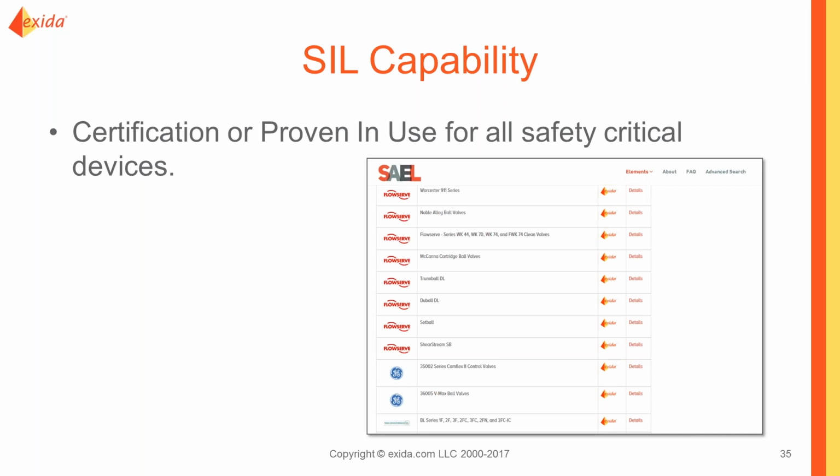collect information as some of the evidence that the devices are suitable for the design, and putting it together, because that is one of the things in the FSA 3 we should be validating. We've met the SRS, we did a correct design, the SIL verification is correct, so we meet probabilistic numbers, we meet architectural requirements, we meet SIL capability requirements.